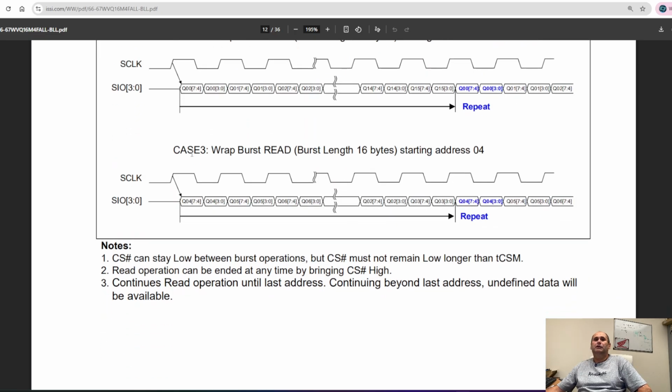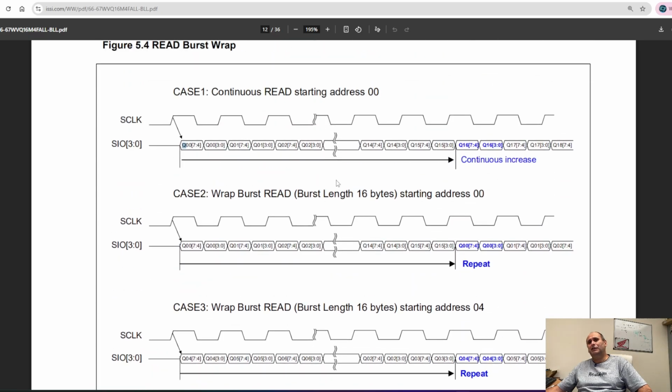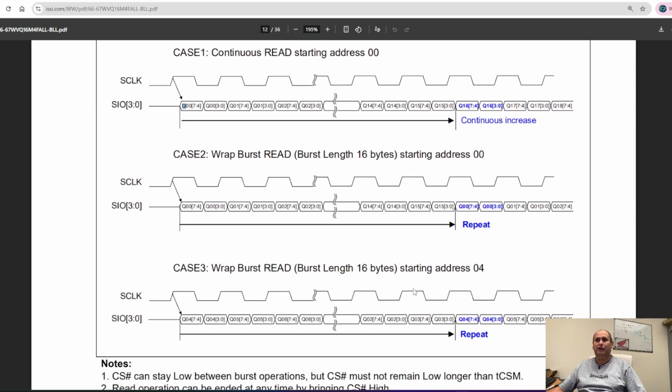Okay, now, it has a use case again for video controllers if you want to double a line. So you have a line of video and you want to double the line for whatever reason, like upscaling a video for a retro computer, let's say, right? So you have like, I don't know, 400 or 320 lines on an old computer. You want to make them 640, right? To be compatible with the VGA. This is perfect for that, because you have a line of video here and you keep reading the same line twice, right?